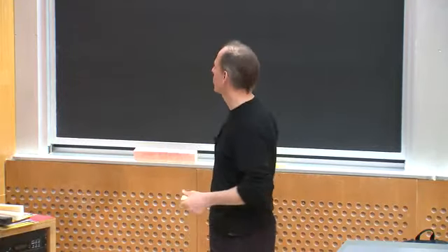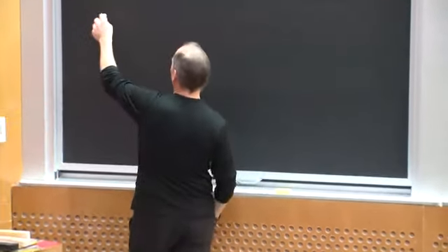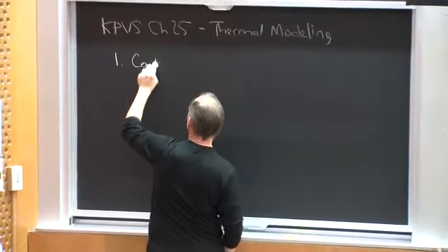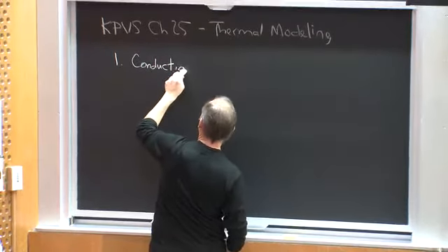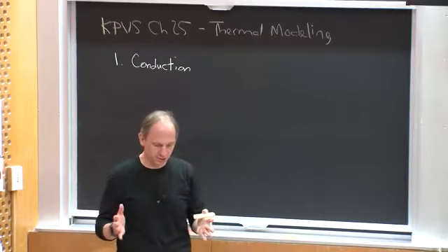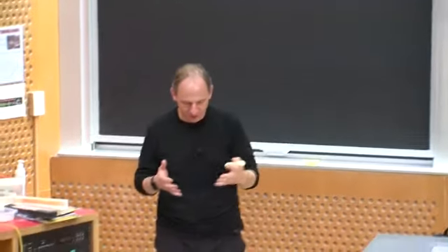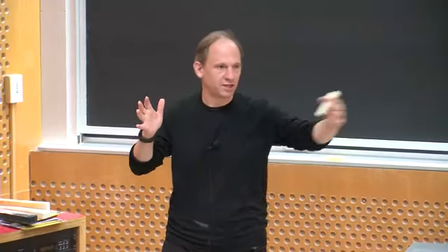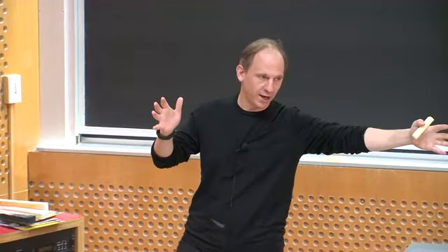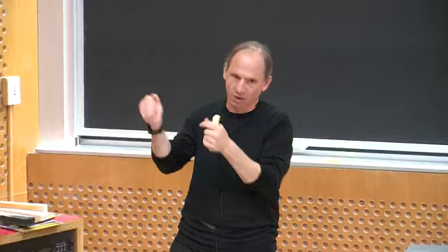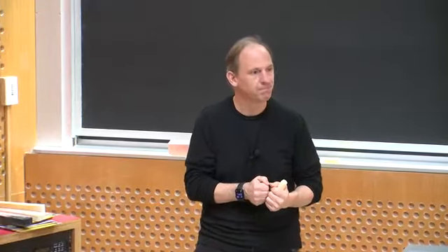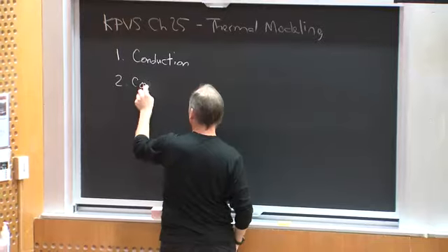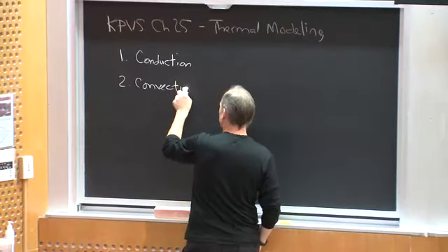Okay? And there's really three fundamental ways you can do that. You can do it through conduction. Conduction is simply, if I think of heat as being vibrations of particles, I can let the heat conduct through some heat conductor and be carried away, so some physical element, like a piece of metal, will carry heat along it, okay? I can do it by convection, right?